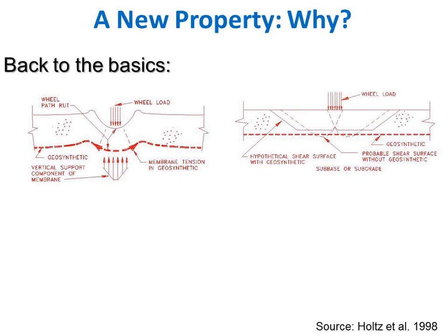One mechanism says the following. If we have a base, granular material, and we have a reinforcement, then with the deformations we will have a membrane effect. So that we will develop tensile forces within the reinforcement, and the vertical component of those tensile forces will help improve the performance of the pavement.